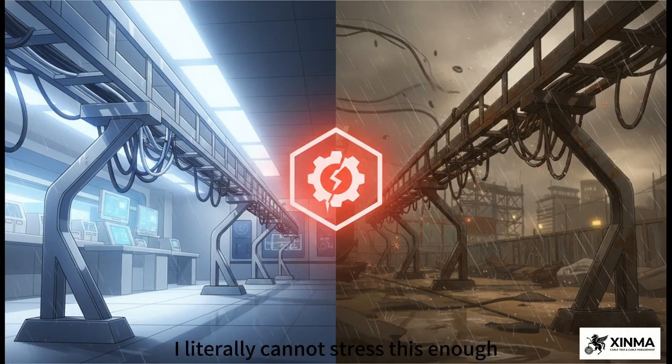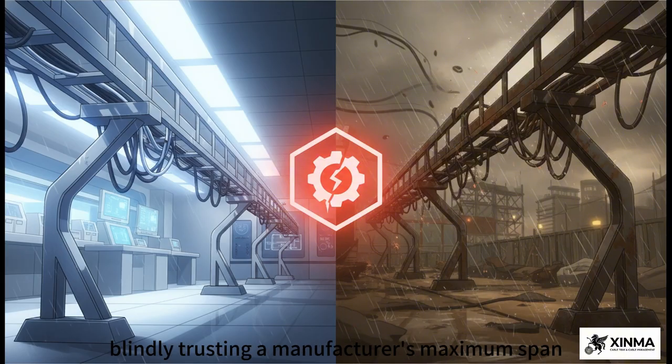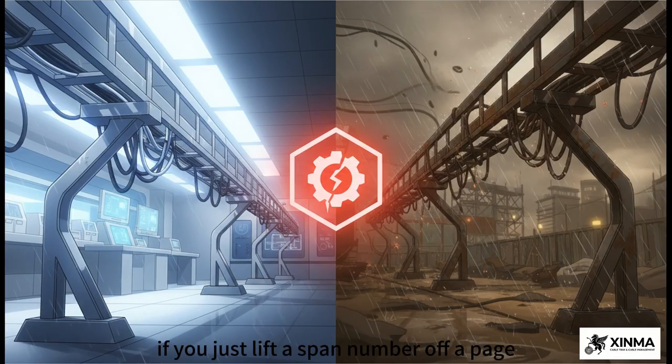I literally cannot stress this enough. What you see for a catalog span does not equal actual structural performance. Blindly trusting a manufacturer's maximum span without accounting for your specific engineering variables is just a fast track to structural failure. You have to remember, catalogs offer a baseline under perfect, controlled laboratory conditions. Out in the real world, if you just lift a span number off a page without auditing the actual environment it's going into, you are taking a massive financial and safety risk.